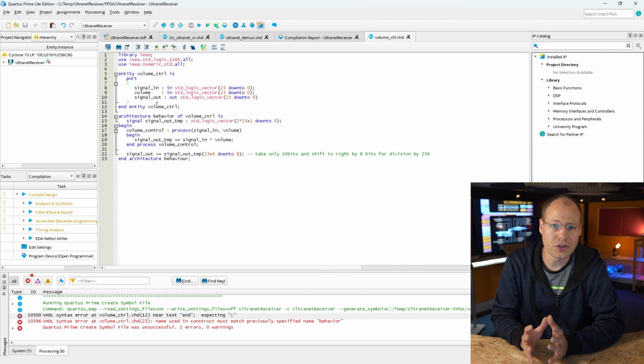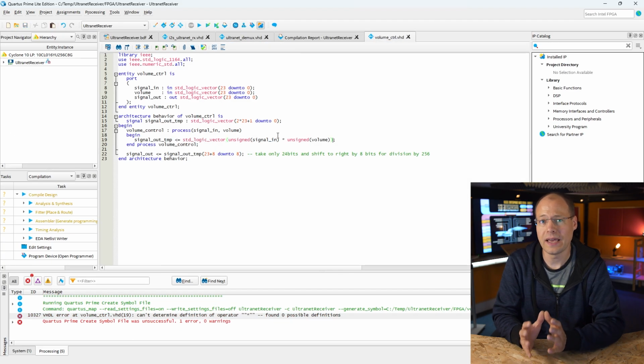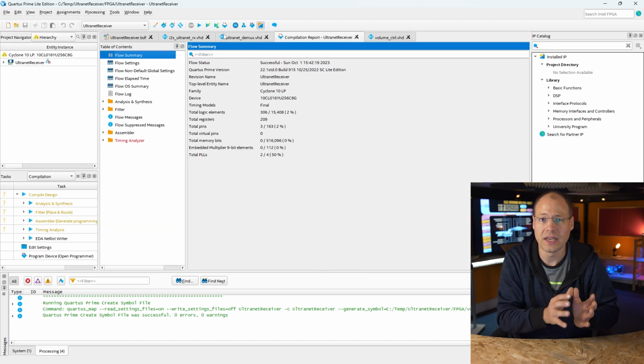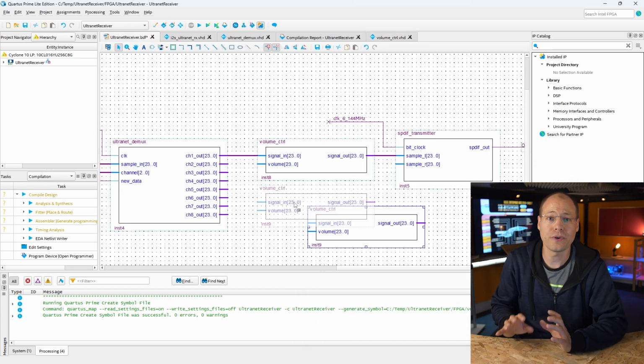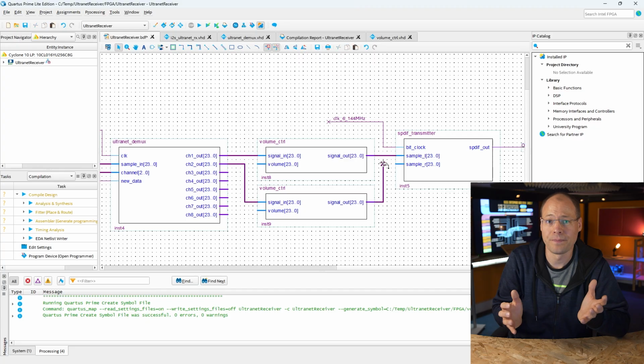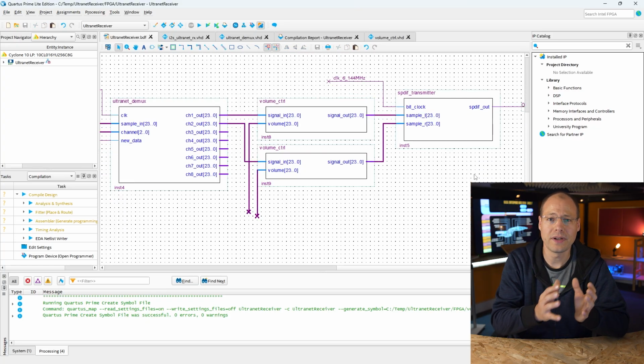So we create a logic block that provides an audio sample and single multiplication values, each for left and right. Here we can also provide further values, for example, for auxiliary paths. On the output, we now have separated audio samples for left and right. Our audio engine is now almost ready. The only thing missing is the connection to the computer.